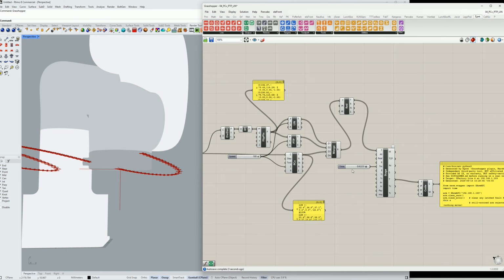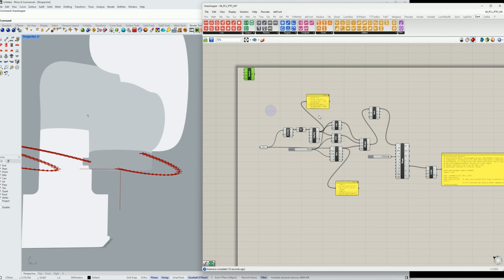So what if we want to consider a tool, like the vacuum gripper or a welding tip or something? I don't think you're welding with any of the UFactory, but maybe. But we need to tell the toolpath planners what that offset is of the tip so we can make tool pathing for it.